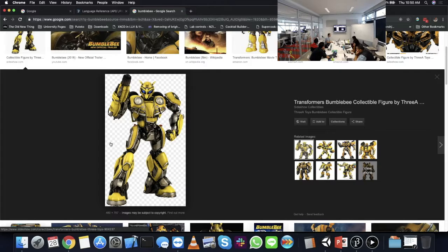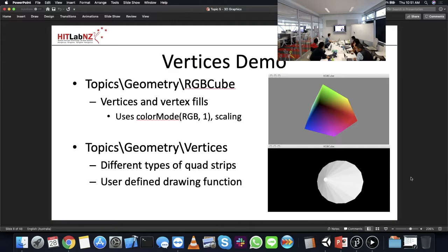So Shun will often do a first pass with automatic stuff at a low threshold, which might take it from 100 million polygons, or 100 million triangles, down to 10 million or 1 million. And then to get it from 1 million to 100,000, he does it manually from there. And it takes a very long time, but that's life.